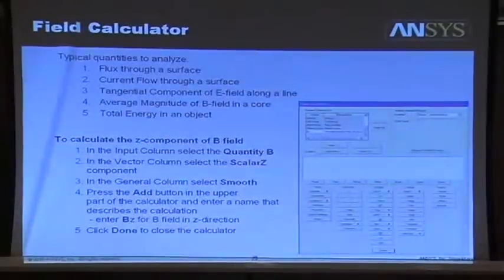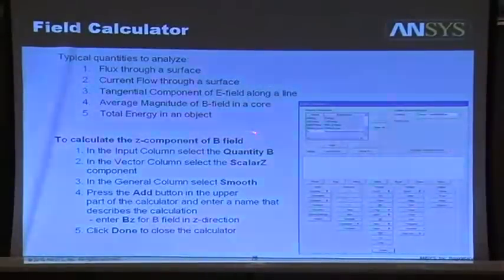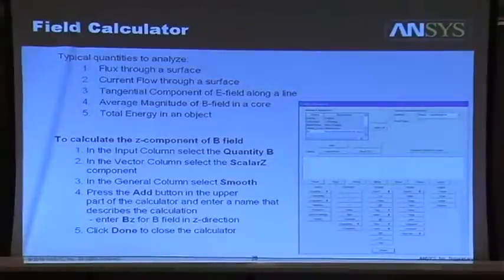This is a very good dynamic tool that we have, that is called a calculator. And with this calculator, if you are well versed with electromagnetics, you can extract the components from the FE domain. Whatever leakages we talk about, leakage factors, those come from some assumptions. But if you go from the finite element domain, these assumptions will not be there, and it will be more realistic.